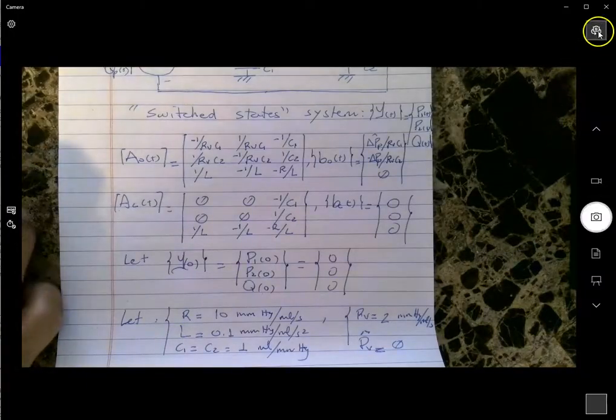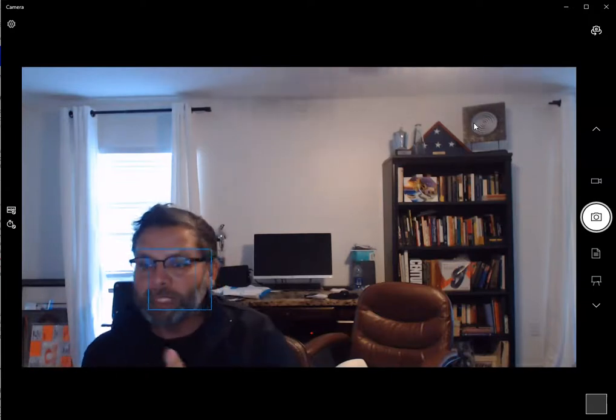So this is what I wanted to cover today, essentially solving the same problem while being able to afford more efficiency, because with adaptive time stepping, we don't need to use brute force to shrink the size of delta T to a very small value all the time. There are instances within the solution process where a large delta T is good enough, but there are instances where a lot of things are happening, like switching from one state to another, where you actually need to shrink the size of delta T, and this is what we effectively did. Not only that, we did it in a smart way by controlling the error, by ensuring that we're keeping within a tolerance that we pre-impose in the solution process.